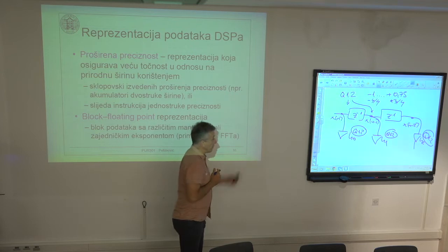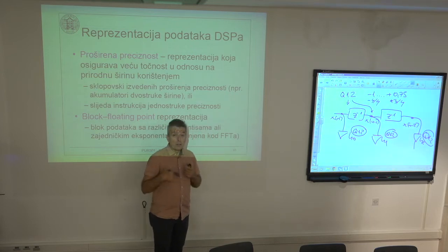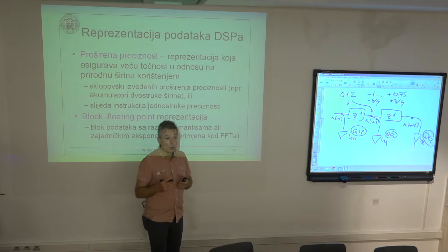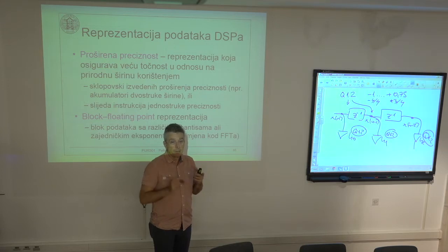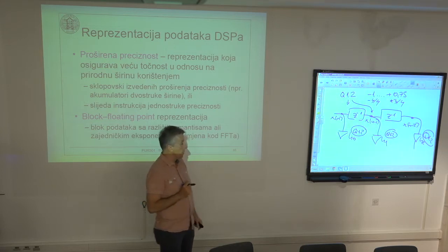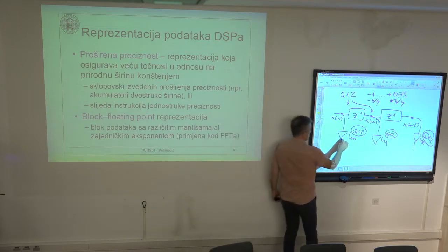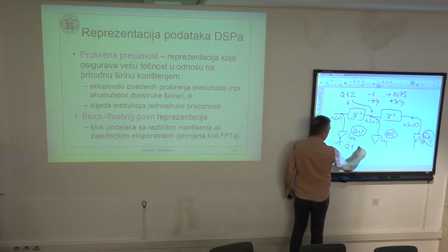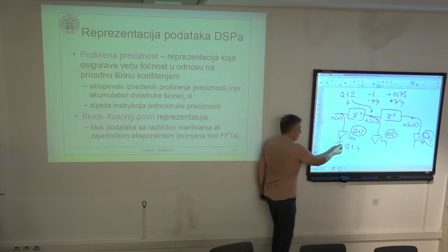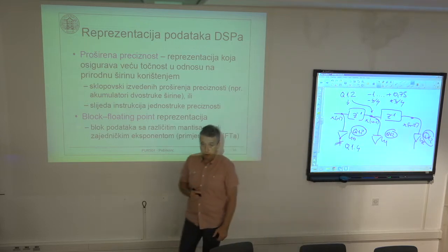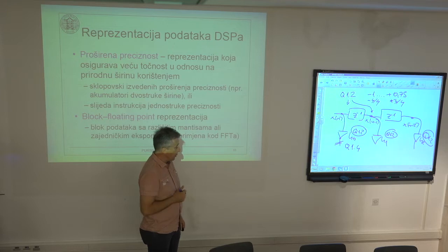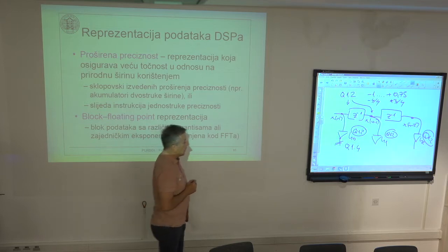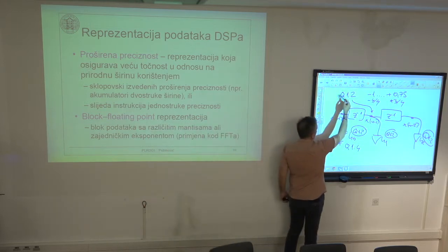And to get rid of this double sign bit, if I use the fixed point multiplier, I have to shift the product 1 bit to the left. In this case, the decimal point is placed again after the first bit. So I would have the product that is Q1.4. So after this left shift, I have the double precision, I can denote it with this double line, double dash. So I have this double precision Q1.4 as a result of multiplication of two arguments.